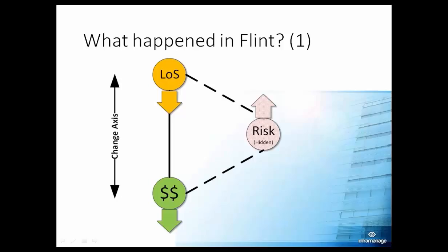Well, there are ways you can get your lubricant analyzed, and there are companies that will do that. You can send off your lubricant and get it analyzed for how it is performing, whether it is lasting, etc. And they were able to do these studies to show that the rate of lubrication in every case was more frequent than it needed to be. So through the study of that particular information for their own exact utility, they could change the lubrication schedule, which can be a significant amount of money because it takes time to perform the maintenance, and it also costs money to get the new lubricant, dispose of the old lubricant, etc. So they were able to figure out by doing that special study that the right amount of lubrication was different than what they were doing, and they could change those schedules.